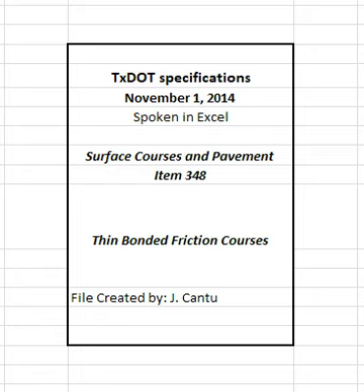2.4.2 Asphalt rubber, AR, binder. Provide AR binder that meets the Type I or Type II requirements of Section 300.2.9, Asphalt Rubber Binders, when AR is specified unless otherwise shown on the plans. Use at least 15% by weight of crumb rubber modifier, CRM, that meets the Grade B or Grade C requirements of Section 300.2.7, Crumb Rubber Modifier, unless otherwise shown on the plans.